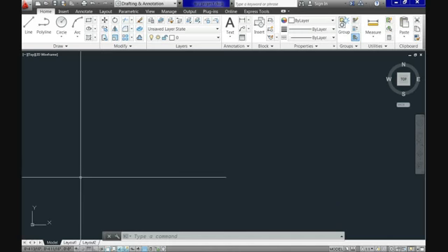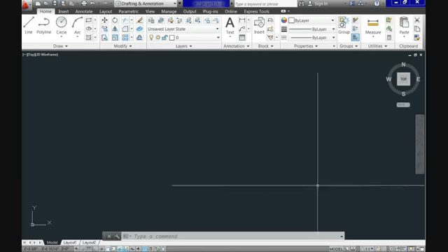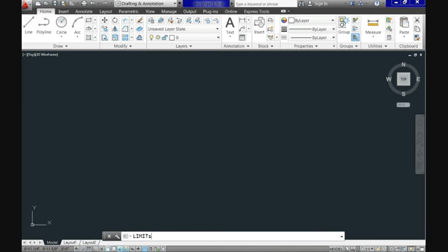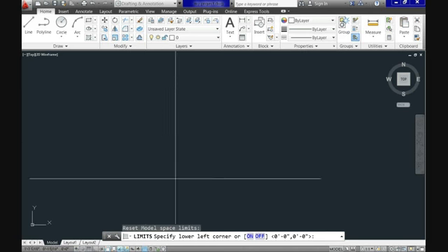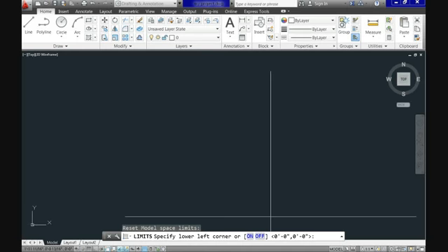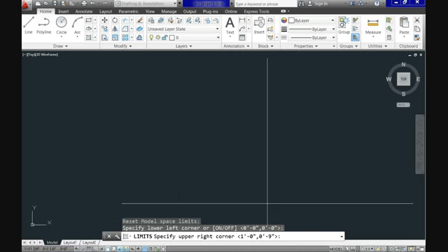The other basic setting is the limits of the drawing. You can access that, you can specify that limit by typing in your keyboard limits. When you hit enter, you see that it says limits, specify lower left corner, or gives you on or off. You can turn on or off this setting, and then you can input there the limits.